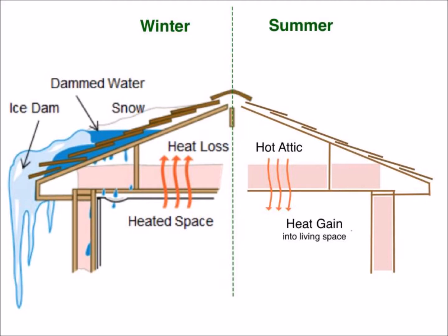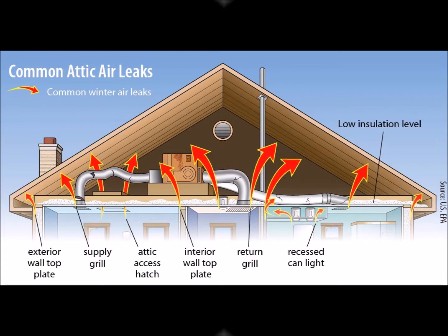The materials for sealing air leakage pathways should include products that are durable and compatible with the joint materials, especially around hot surfaces. Some of these examples include spray polyurethane foam, construction adhesives, gaskets, sill sealers, high-quality caulks, tapes, as well as a number of specialty products such as gasketed electrical receptacles, switches, and ceiling light fixtures.